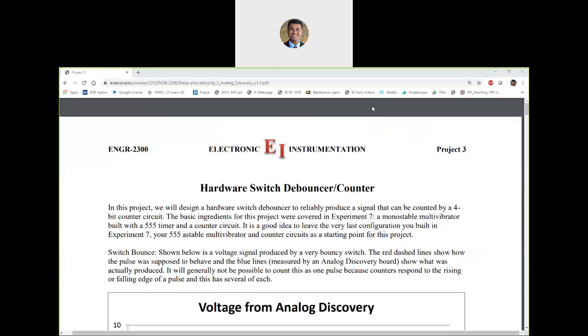Our goal is going to be to keep it on in one state for 100 milliseconds, but we can control how long we want that by adjusting the values of R1 and C1. So the goal is not to discharge C1 quickly. We are going to choose very high values for R1 and C1 to slow down that discharge. Let's see, pin 6 and 7 are connected together. That's another difference between the monostable and astable mode. Pin 6, as you guys know, that's the input to the threshold comparator, and pin 7 is the discharge pin.